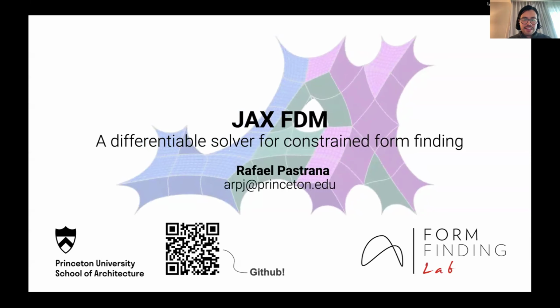which for the force density method are the force densities Q defined on the bars of the graph, the applied loads P, and the positions of the supports XS. So if you input some graph and a set of parameters theta to the box, then you shake the blue box, then you'll magically get an efficient shape that is compression only, tension only, or combinations of the two, that we denote here by capital X, right?